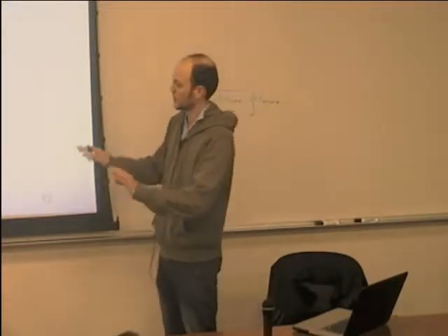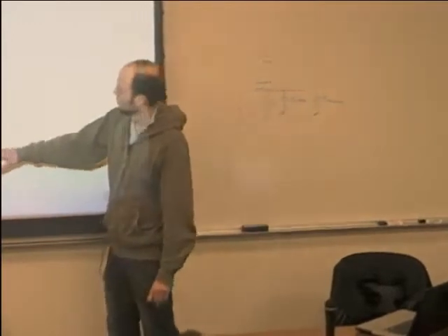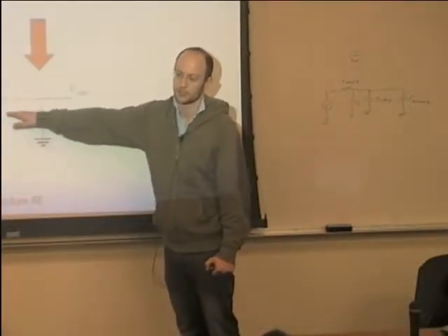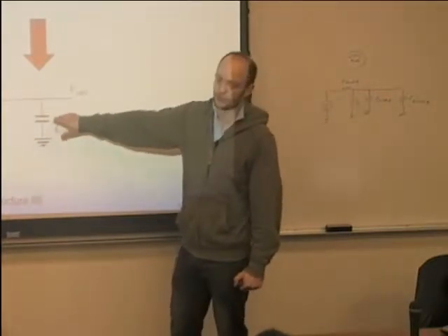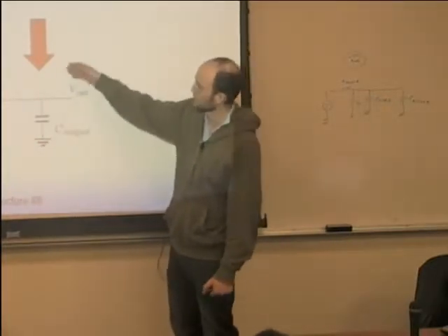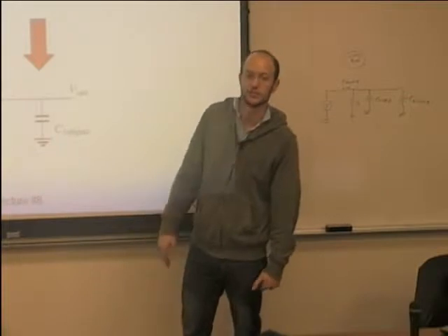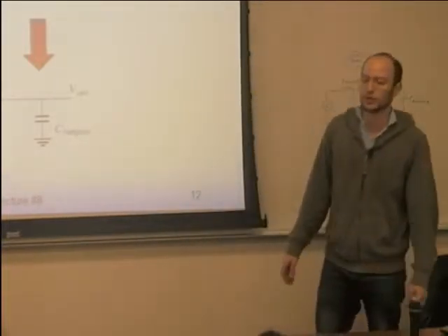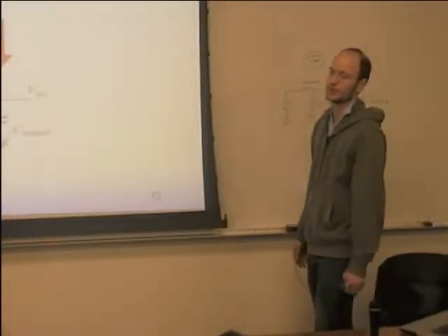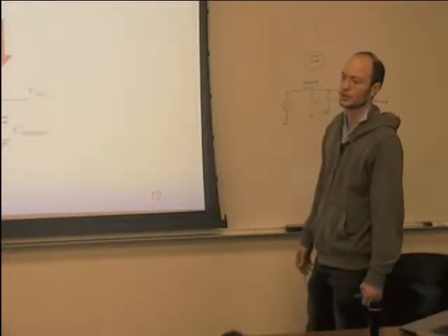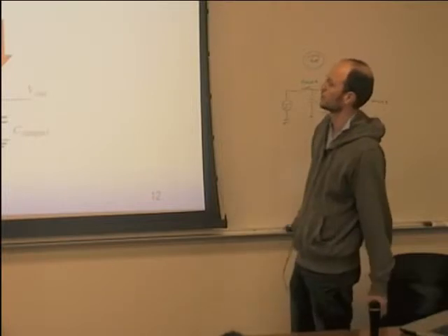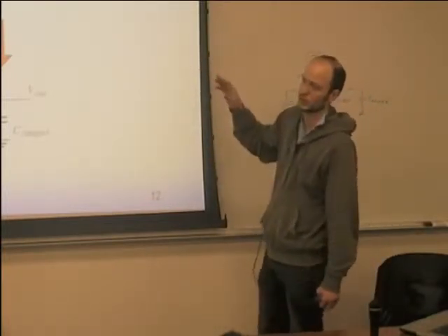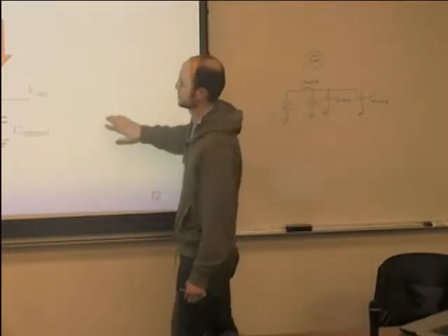Okay, so let's do another example. There is already a resistor here, the resistor of the driver, right? So one thing that could be reasonable is to say, well, if the resistance of the wire is 1/100 of the resistance of the driver, then it will change the delay by 1%. Fine, we don't really need to worry about it, because probably the uncertainty in the delay of the driver is larger than 1% anyway.